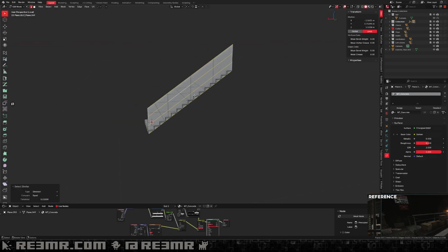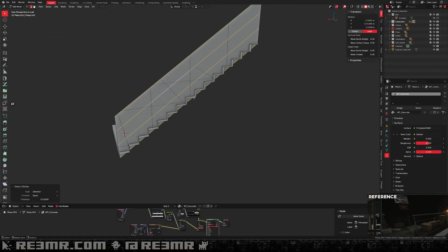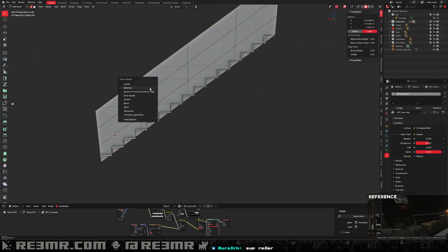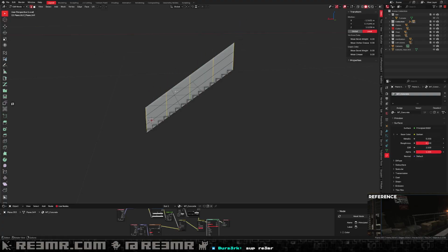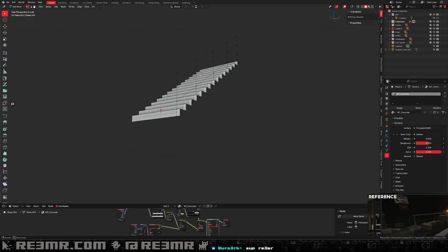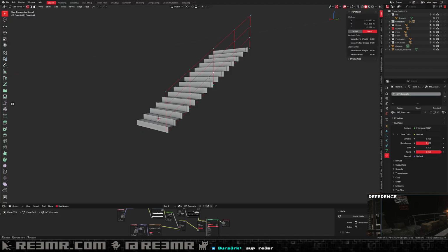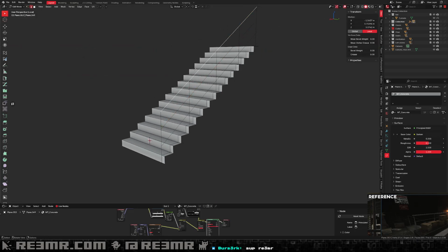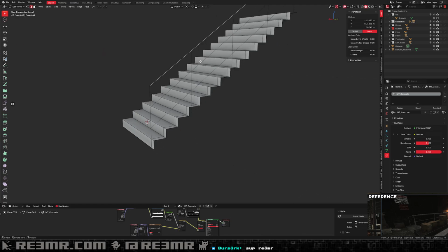Like this, select by direction, select all those edges. Press Y to split them off. And select this one by selection, press Y, split them off. Then I'm just going to select one of these faces, select linked, and delete everything, which gives me only these edges left, right? But these still have all these verts, and I don't want those, right? So I'm just going to press X and limited dissolve. That removes all those extra verts in between. So now these are all split individual pieces.